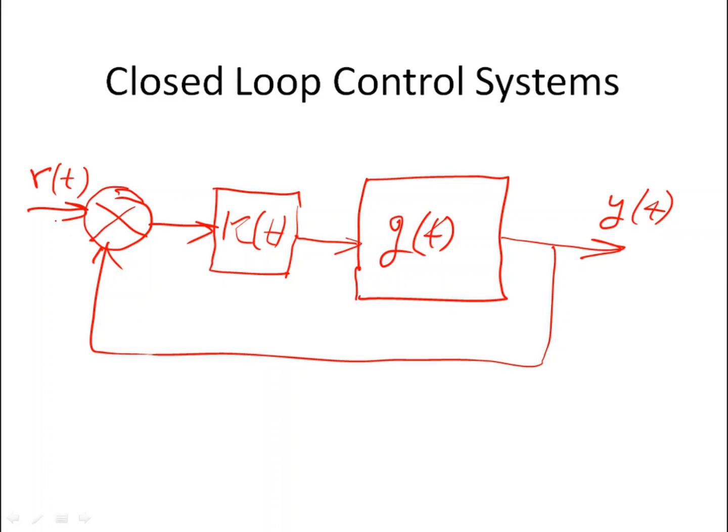As I am comparing, this is plus, this is minus, so you have to subtract the measured output from the reference input. So when you are subtracting, naturally we are getting a difference. This point we are defining as ET, the error signal. The output of the controller, as we studied earlier, is UT. UT is also called the control signal, the output YT, the reference input RT.